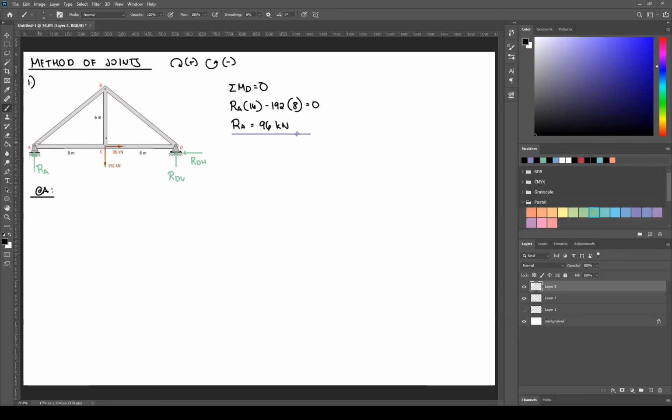So draw the free body diagram at joint A. So you have this. Okay. I like to draw the line of actions first. RA here is upward, so just copy that direction, RA. Now these lines represent your force in member AD and member AC.